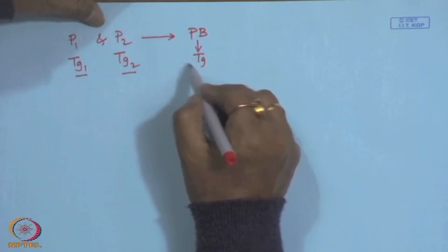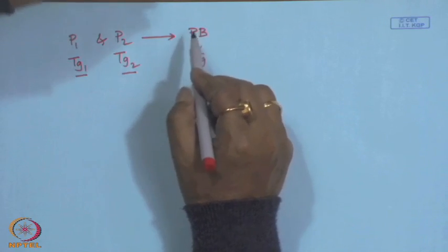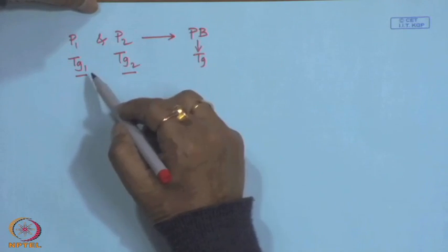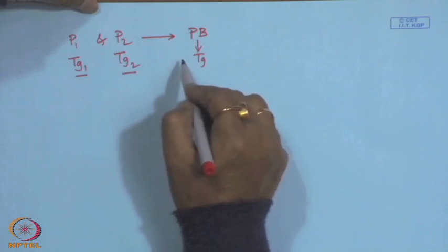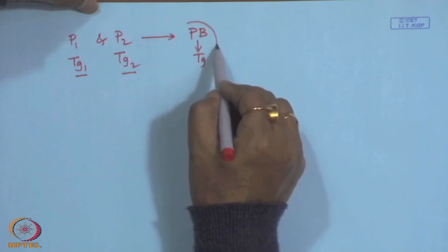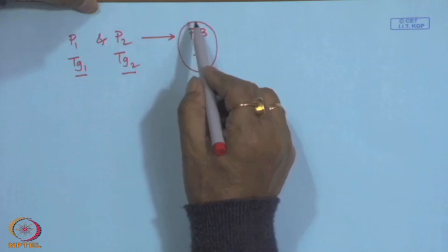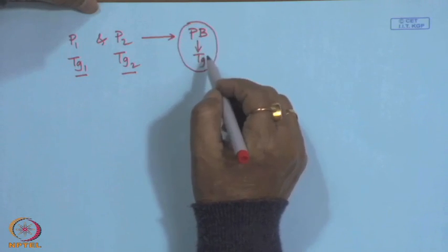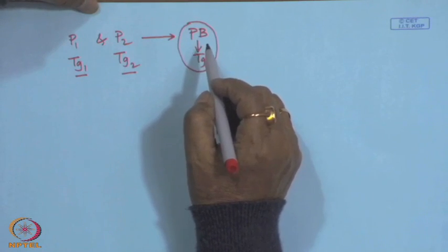Having only one Tg of the polymer blend, although polymers of two different Tgs were used, gives a good indication of miscibility of the components in the blend. That happens due to the additive effect.